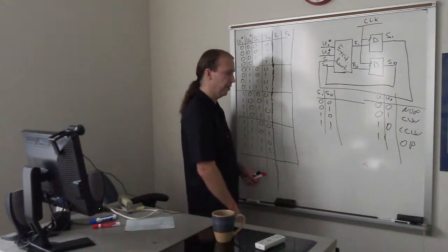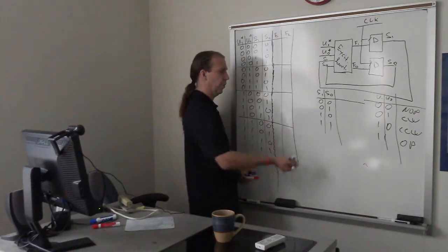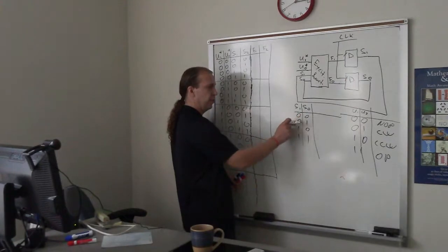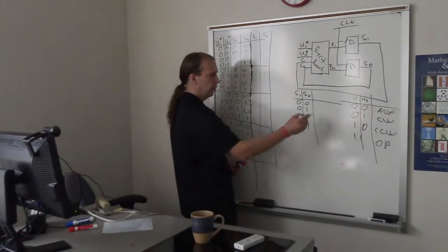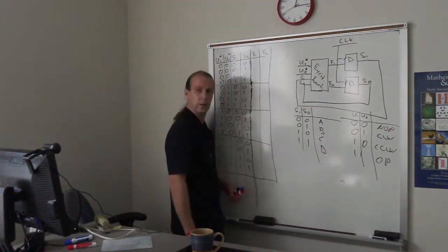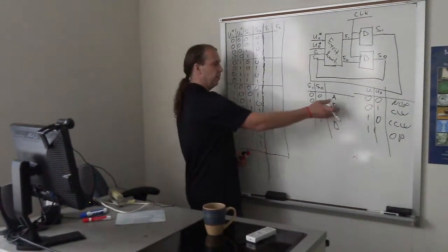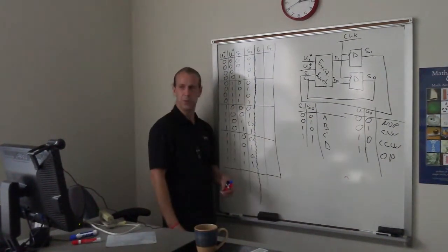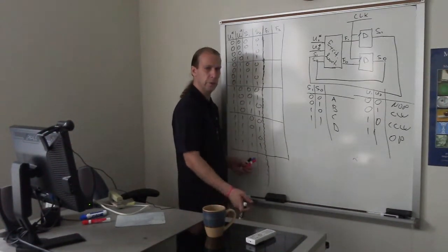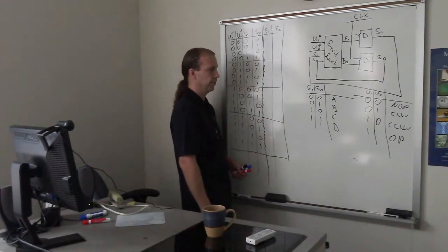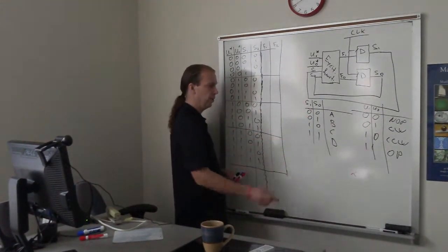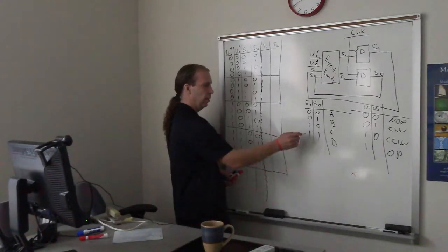Let us just name them in order. But again, it is not important how we assign combinations of bits to a particular state, as long as we list all states A, B, C, D, we are good. We can list, for example, those states as C, B, D, A. But it probably doesn't make much sense unless we have a reason for that. So we list 0, 0 to be A, 0, 1 to be B, 1, 0 to be C, 1, 1 to be D.